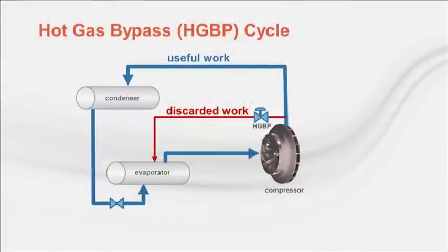So if the preceding kW per ton performance trend is likely the best we can expect from a modulation system, what's the worst? For this case, let's examine a compression device that does not modulate, but instead uses capacity control external to the compressor. The most common form of this is hot gas bypass. It regulates the compressor capacity by selectively bypassing compressed gas back to the suction.